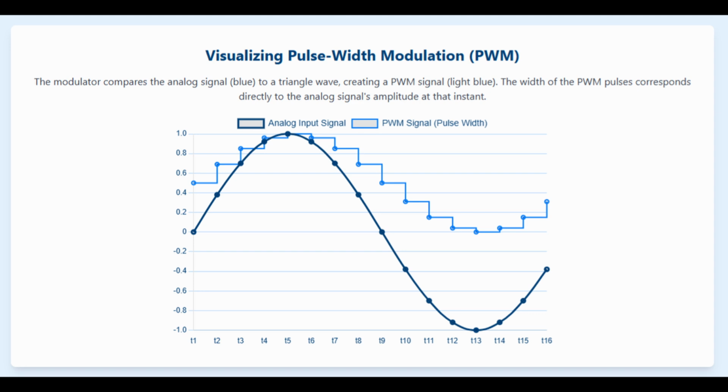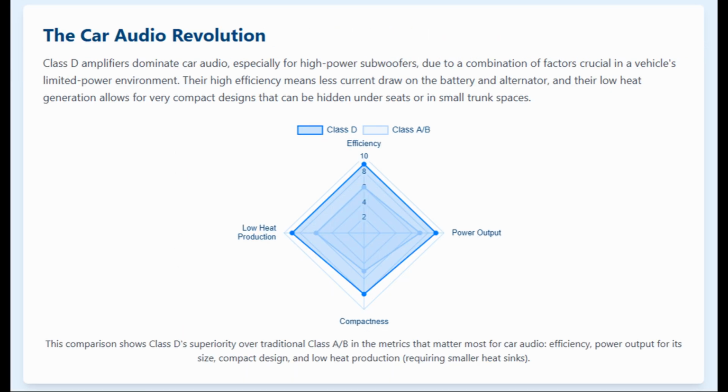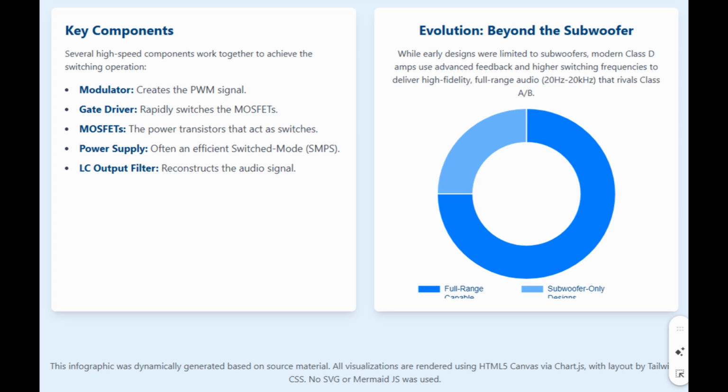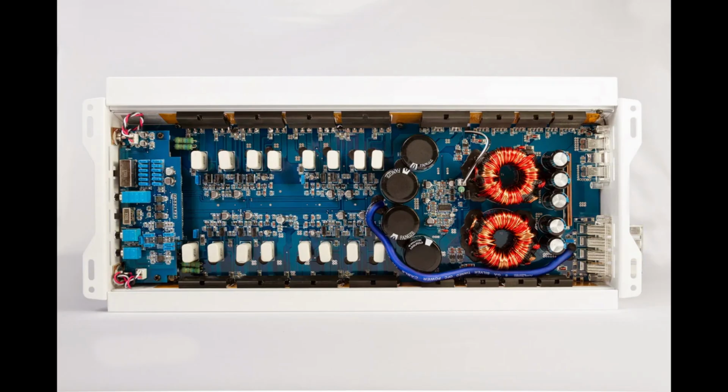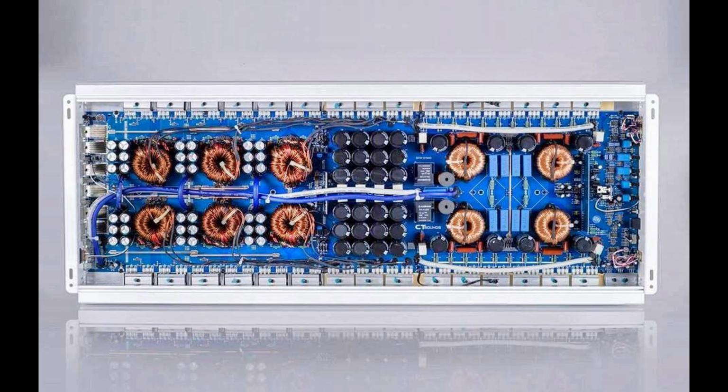It is, and it has a huge economic impact too. Because the output is already much cleaner, you don't need those big, complex, expensive LC filters on the output anymore. The inductor-capacitor filters. Yeah, those can be bulky and costly. With multi-level modulation, you can often just use simple, tiny, cheap ferrite beads instead, so it shrinks the size and the cost. So better material with GaN lets you switch fast without penalties, and smarter architecture, like multi-level, makes the output cleaner and cheaper to filter.